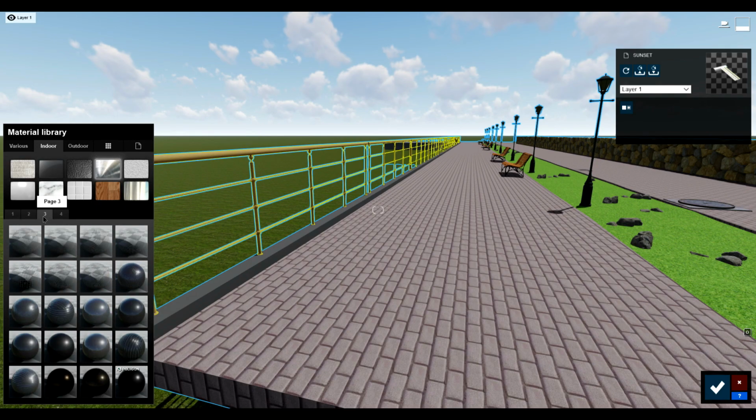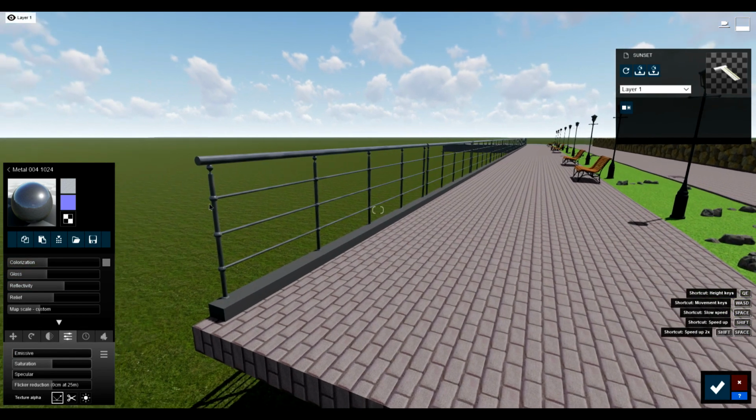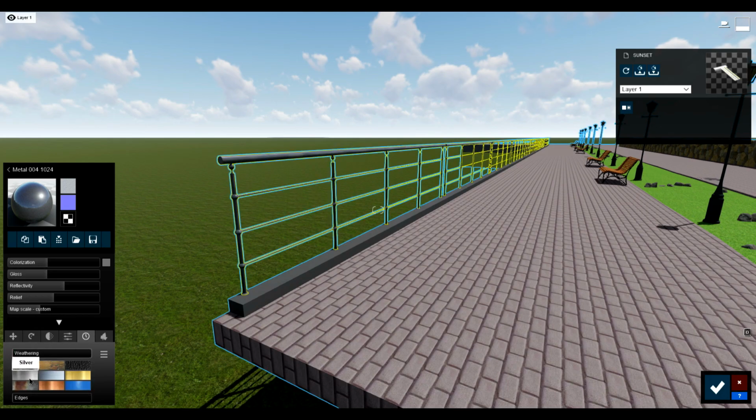Then go to Materials Library and apply materials to the scene. Lumion has already pretty good materials installed. Just select and put it on your model. Another tip is to always use the weathering and edges sliders on your materials. It will have a good realistic effect on it.